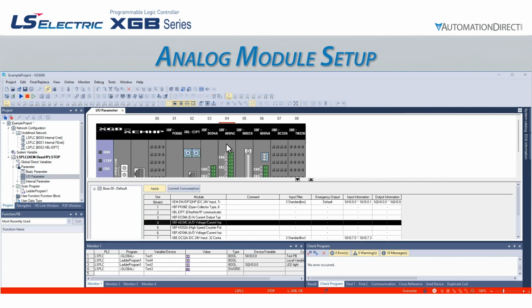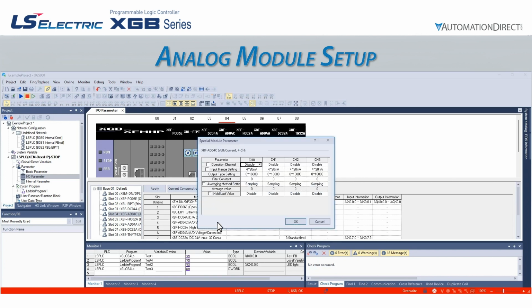We have an analog input module in slot 4. To configure the module, we will double-click anywhere on the slot 4 row. This will open the Special Module Parameter pop-up window. For this module, we have 4 total channels. We can adjust the operation channel setting, the input range setting, the output type setting, the signal filtering, the averaging method, and the hold last value setting for some models.